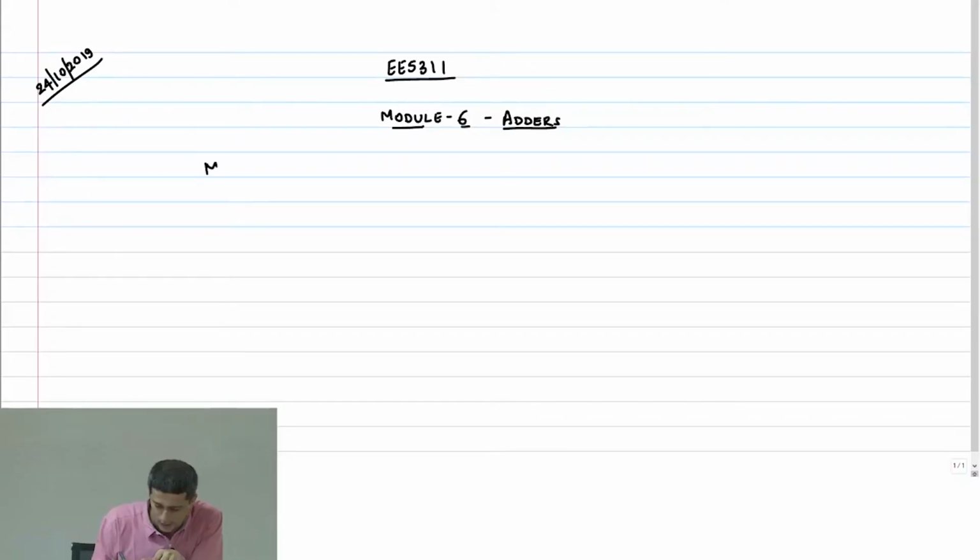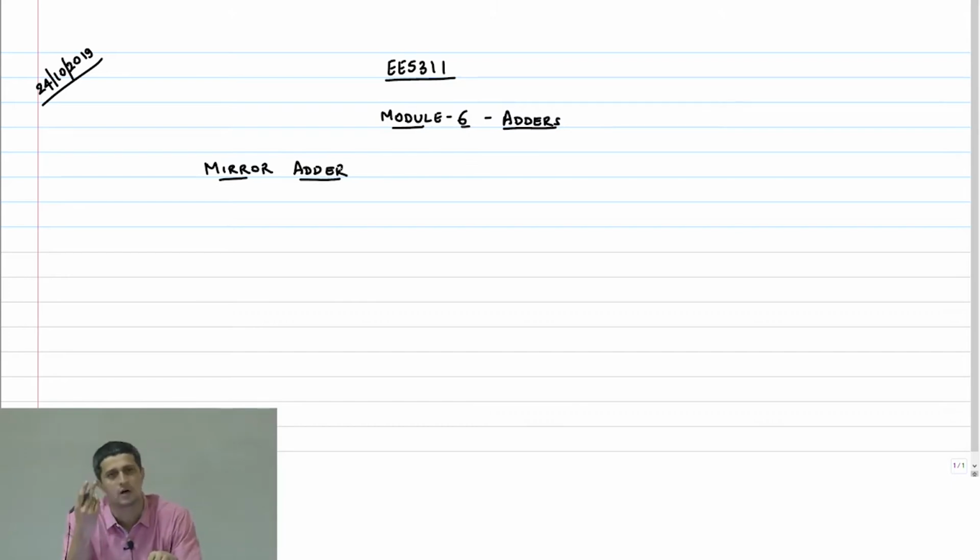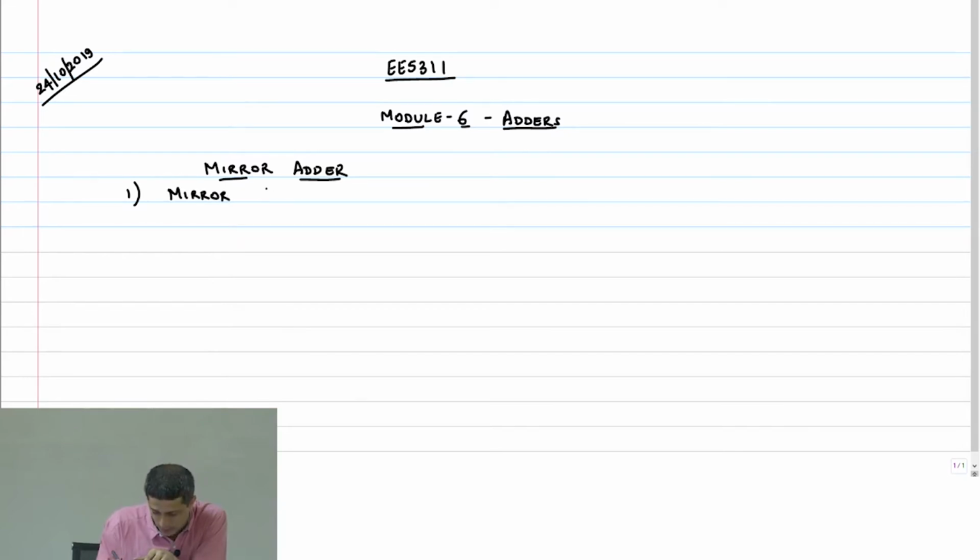Okay, so good morning, and let's proceed with our discussion on the adders. Yesterday we looked at the mirror adder, where we applied all the concepts that we learned in module 4 in order to design this adder very effectively. What were the things that we did? We used the mirror principle, the mirror idea, to reduce the PMOS stack size.